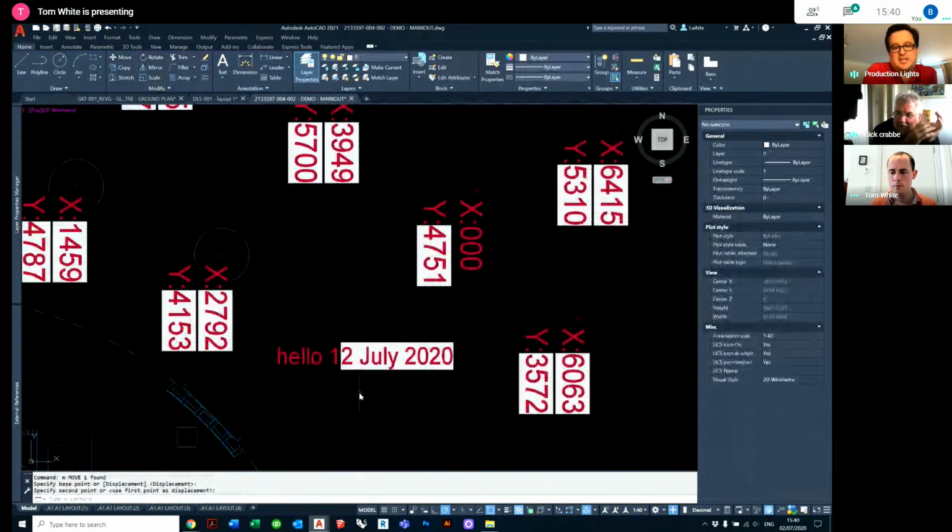It's hugely powerful, the whole field data, because as Tom's layout sheets and stuff like that, he's putting stuff into his layout sheets. So plot date, date of drawing, issue number, all that stuff can be automated. It goes back to the workflow. The more of this you can do that Vectorworks is automatically updating.